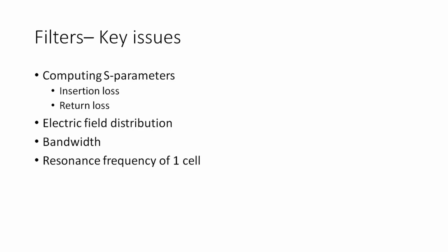Now, the key issues that engineers face while designing these filters is to compute what are known as the S parameters. They would like to understand the losses. What is the insertion loss? What's the return loss? For the frequencies that are of interest to them, they want these losses, the return losses, etc., to be as minimal as possible. And for the frequencies that are not of interest to them, they do want these signals being reflected back. So the product helps you to compute these S parameters.